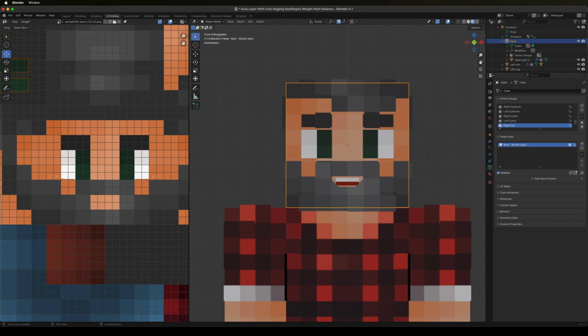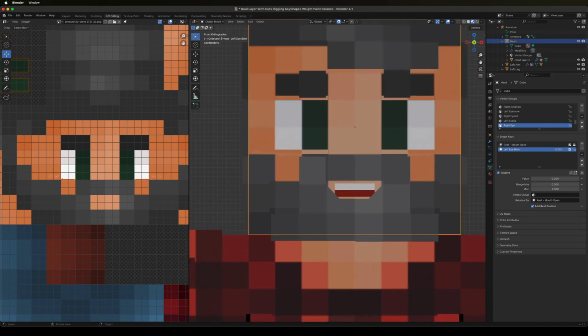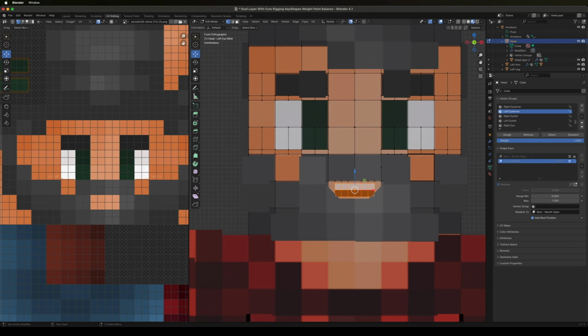A rest position is considered an intermediate point that the facial features can return to or from when not being deformed for an action. In object mode, we add and label the various shape keys we're planning to introduce. As we're not introducing overly complex expressions, we'll set each one as being relative to the original rest shape. Selecting the shape key we'll deform, we now go back into edit mode and start moving the various vertex groups until we have the expression we're after.